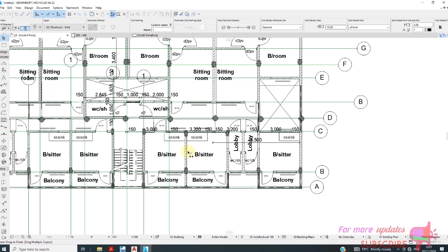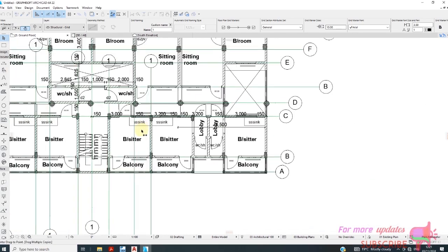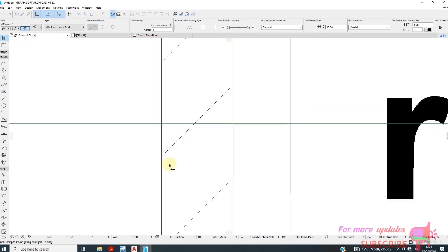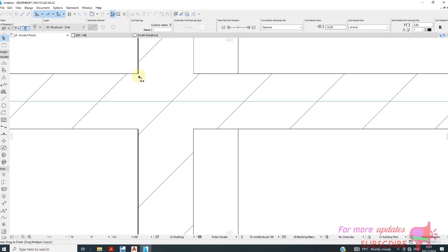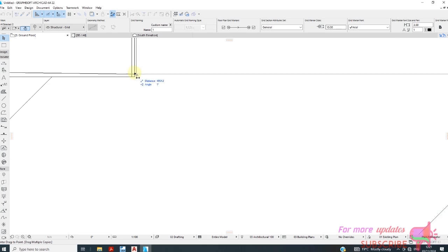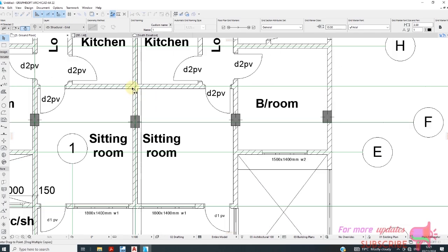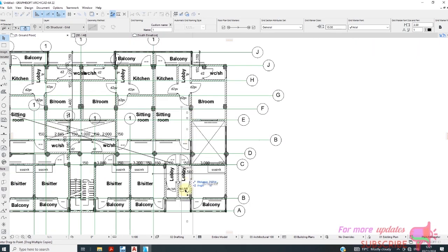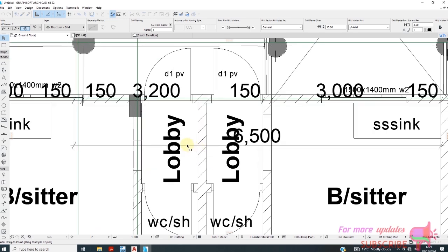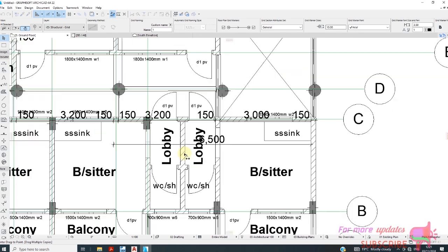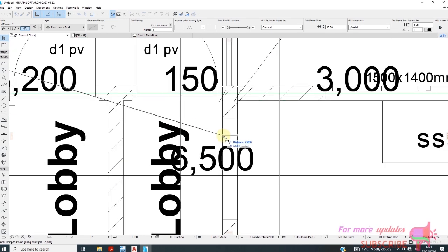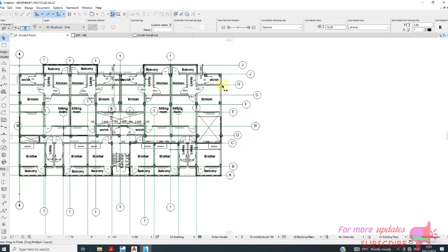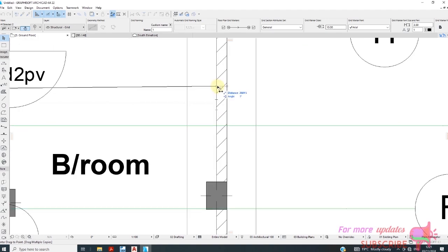Although some walls are not of the same grid line on the lower and the upper side. Here you need to be careful. I would prefer to use this point. Now I know that it's going there. Okay. I have another one here. I'm going to assume this one is a partition. I don't need a grid line for a partition. I can load that slab with that partition, then do the analysis.